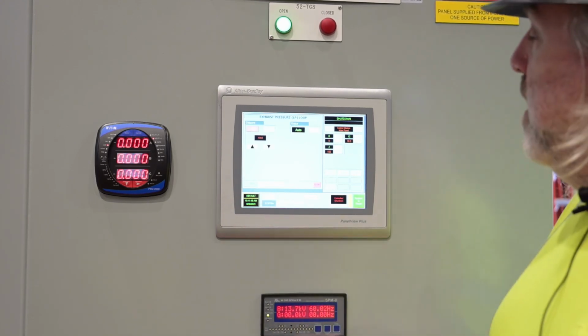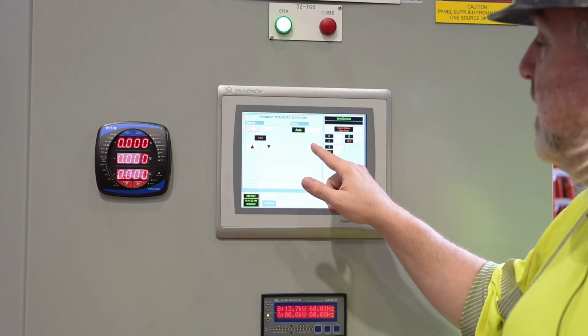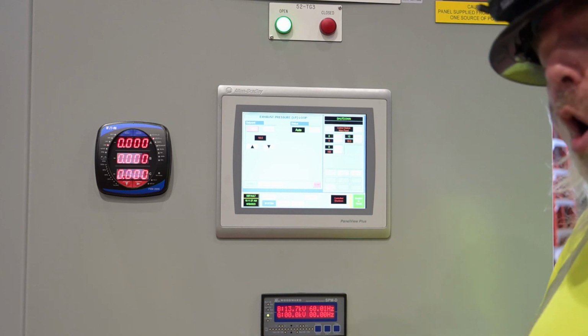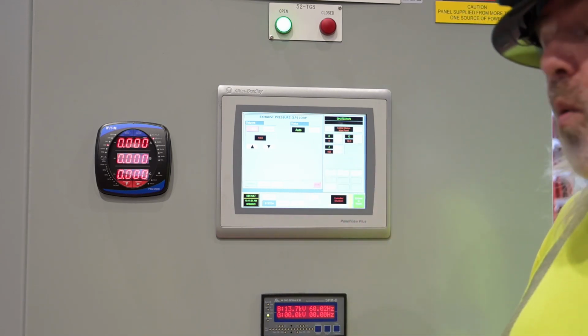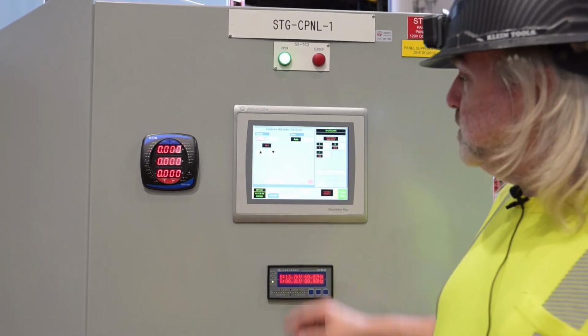For control, you have a status of the control loop itself. In this case, we can see that our control loop is in auto. If the control loop is in manual or override, then you'll also have an alarm to let you know why that is. Once you've cleared that alarm, we can reset the loop back to auto.